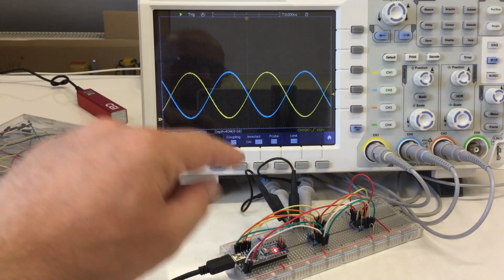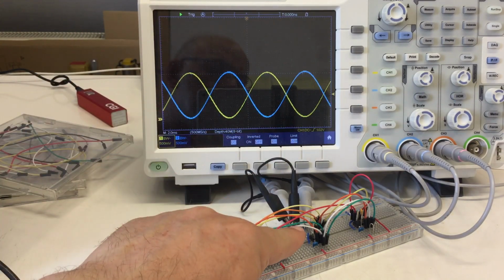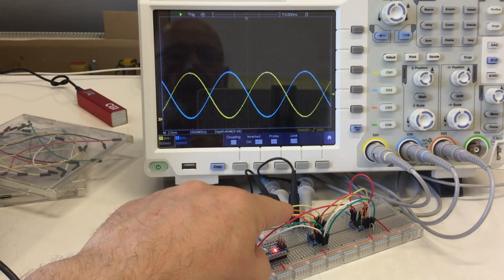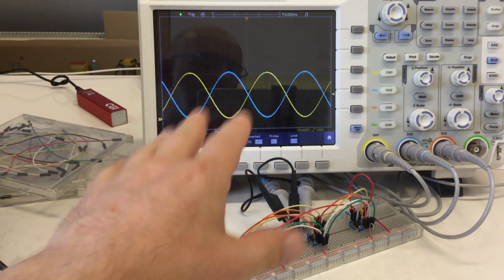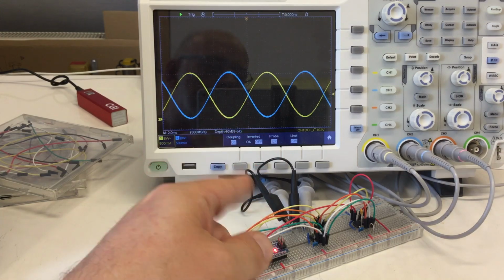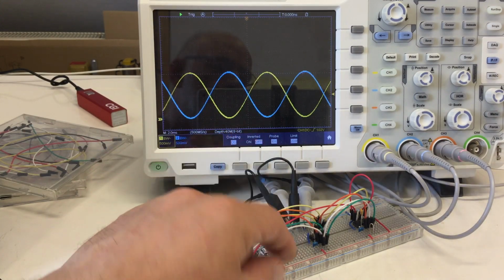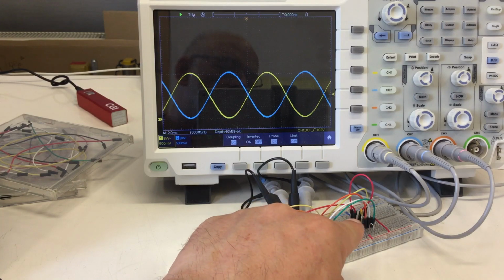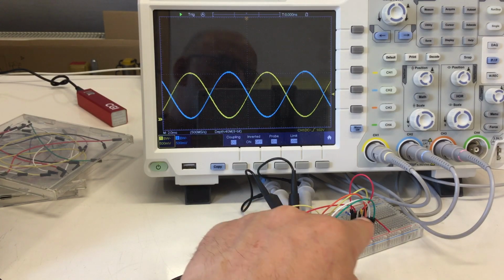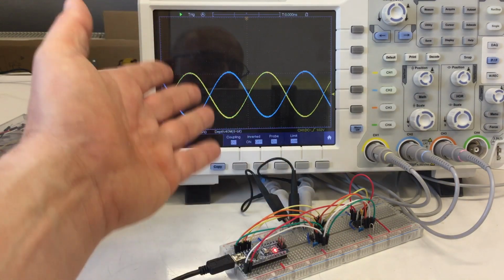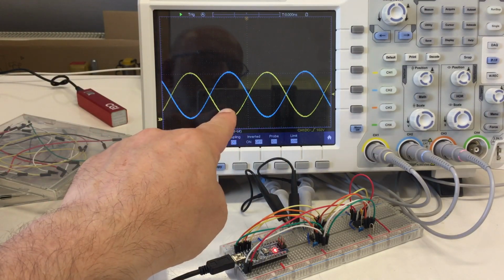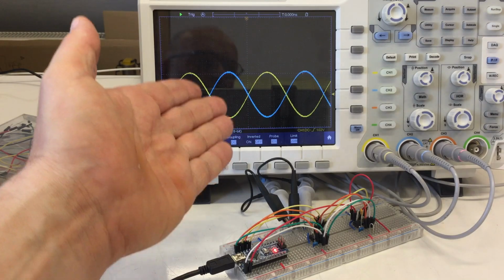Enough about software. I switched back to the MCP4822 with its built-in voltage reference, so I'm using now the code that was commented out in the main loop, and in turn I commented out the code of the MCP4922, and again, of course, we get some nice sine waves. Or do we? Let's zoom in.